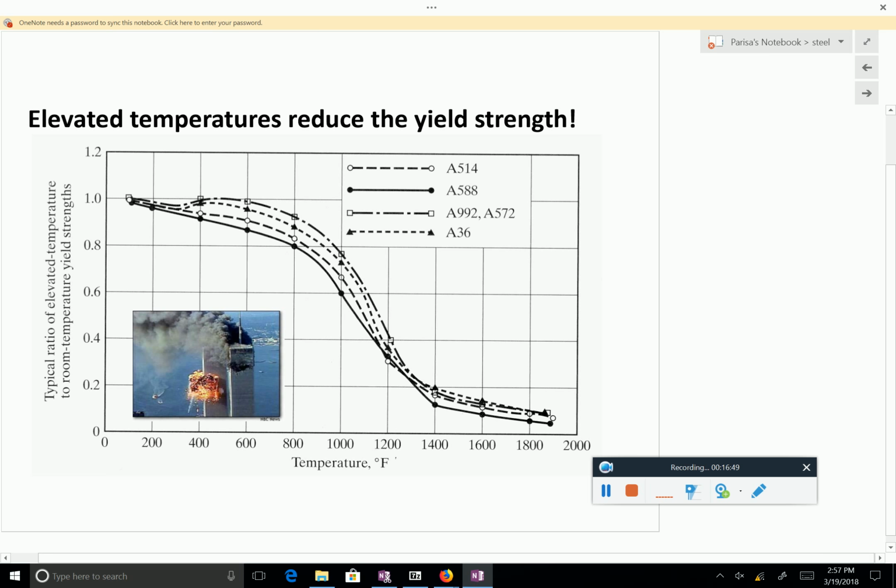It turns out that different types of low carbon steel also have different behaviors, for example, if they're exposed to very high temperatures. Last time I told you, a steel has two big problems. What are the two big problems of a steel? Exactly. Corrosion, you saw that you can add many alloys. I'll show you some other tricks for how you can have a corrosion resistant material. For fire, you kind of have to know what the behavior is.